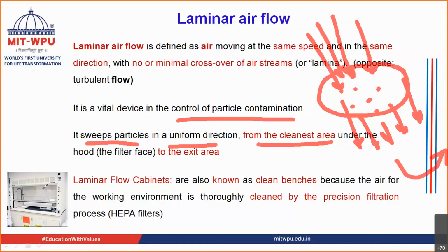There are two types, as I told you: horizontal and vertical. If the air is coming from the top, the particle present over here is going to move along with the air, and then it is going to get removed from the system, from this hood, wherever the critical activities are being carried out.